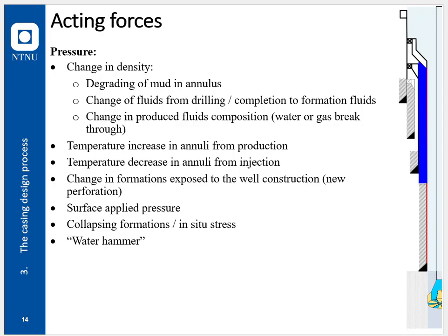It is like a sand plug at the bottom, and the fluid itself has returned to something like 1.03 SG, like seawater or formation fluid, any density that you'll find in your formation fluid on the exposed formations, like what you see in the annulus marked in blue on this drawing.